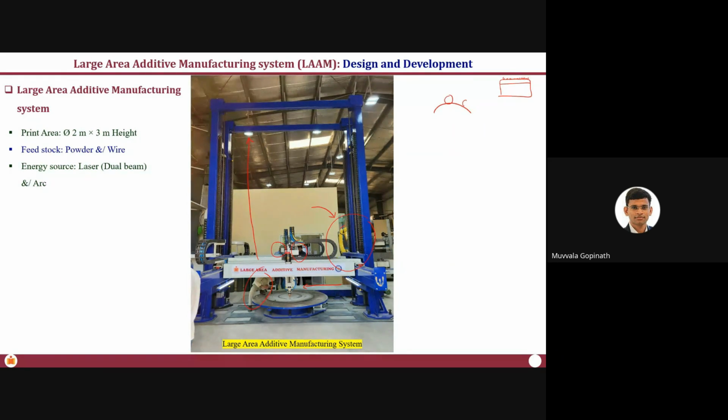And the same is true with the powder bed fusion process also, because typically when we talk about implants, they are made out of the powder bed fusion process. But when you talk about coatings on an implant, that is sometimes made out of DED, sometimes made out of plasma spray coating. So always the interfaces.